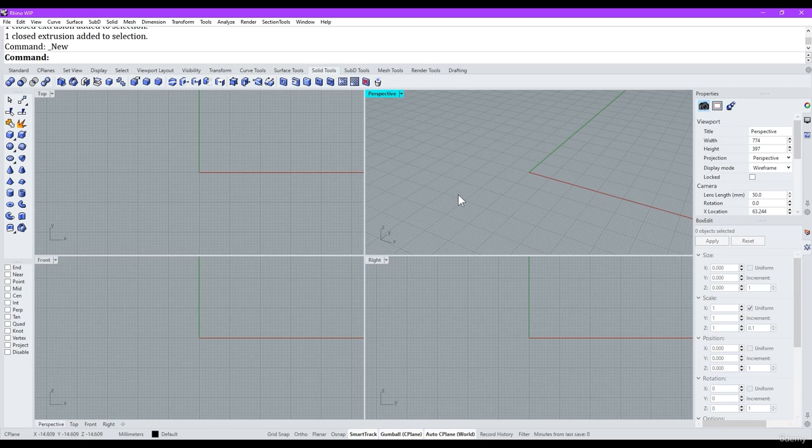And basically, Small Objects Millimeters is going to define in our grid here our units that we're going to be using. So 1 unit is 1 millimeter, and each one of these small squares here is also 1 millimeter. If I scroll out a little bit, we can see that we've got this darker square here, and this indicates that this is 10 units or 10 millimeters across. So you can quite easily see that we've got small millimeter sizes and then bigger 1 centimeter sizes.